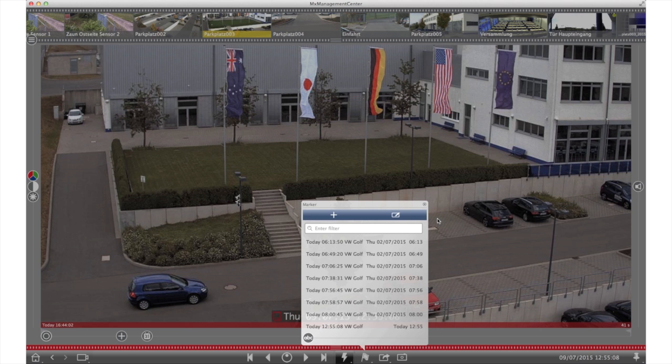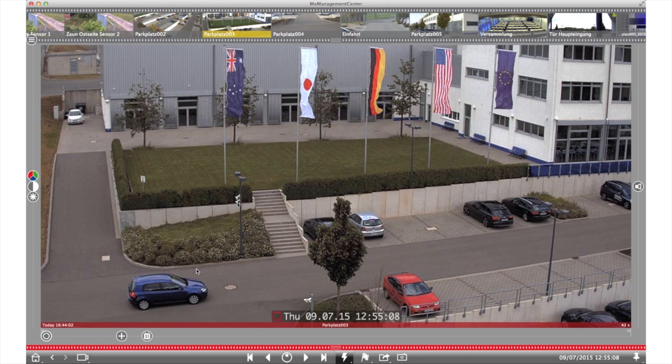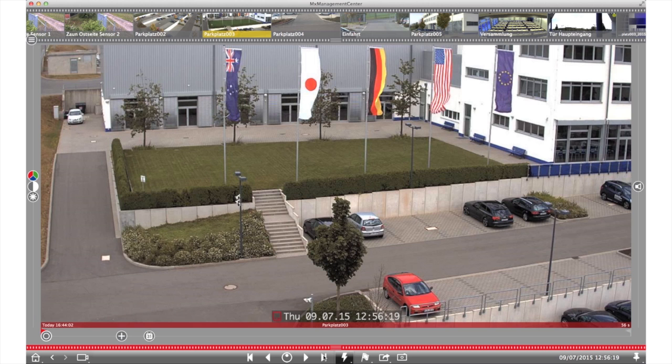If a specific time range is to be exported for the playback, the time range first needs to be specified. To do so, we navigate to the beginning of the sequence and tap the small flag on the left, which marks the beginning. We then navigate to the end of the desired time range and tap the small flag on the right to mark the end. Once this has been specified, the two small flags turn green and the export dialog can be opened.